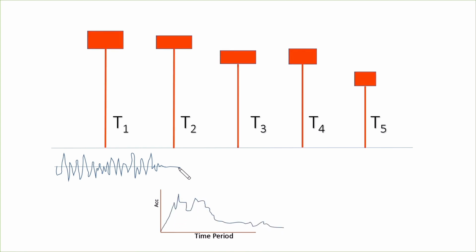And this graph can then be used to check the response of another structure by using the period of that structure and project it here. And this will be the response of that new structure. And we notice in this graph, this is not a smooth graph, and indeed, this is the plot of responses of these oscillators. And in the previous recorded earthquake, like the popular El Centro earthquake, which